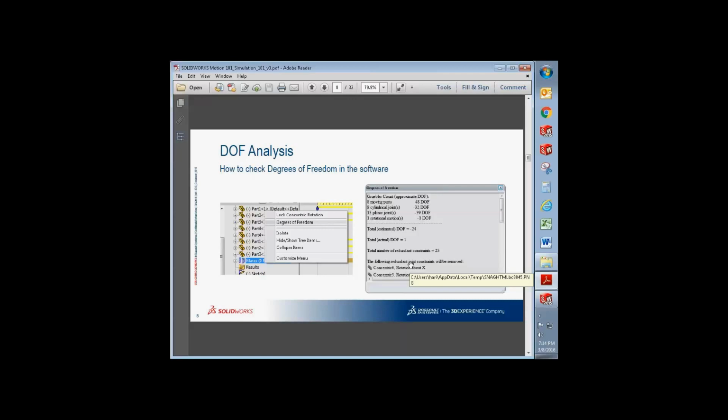And I know Jason's worked with scissor lifts, where it's a symmetric model. On both sides you have similar mates, so you just need one side's mates. And then if I'm using 2 actuators to drive one motion, only one actuator will get all the load. So that's where you would use the force-based function for a motor. So it will compute the forces on both sides. We won't go through that. It's more advanced. I have some examples I will share. I've not shared it here, but I'll send it after the call and see if we can post it, showing how we would tackle that.